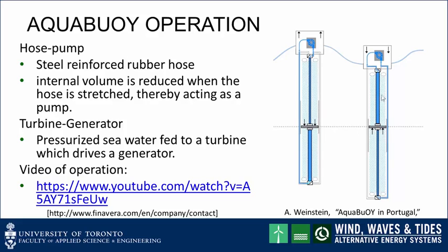As the buoy rides back down the wave, the opposite situation occurs. The piston motion has to move up. It stretches the bottom hose, and so water is pumped then through here up to the turbine, and then it comes back into this section. So a key part of this operation are the two check valves here, which allow for flow.